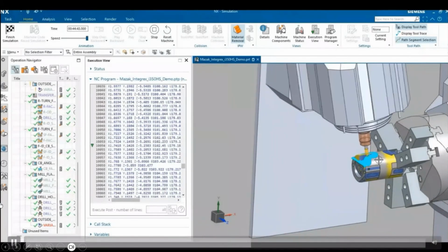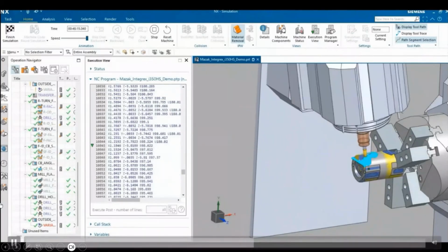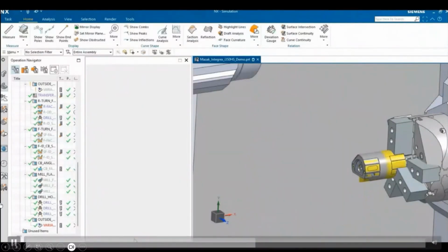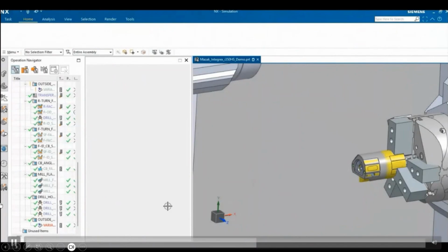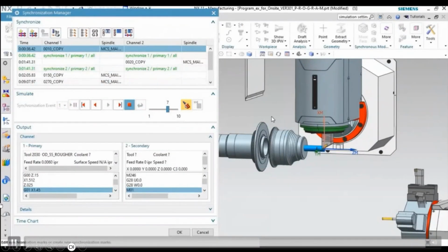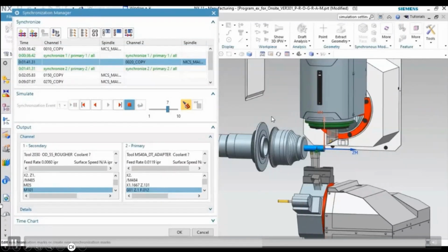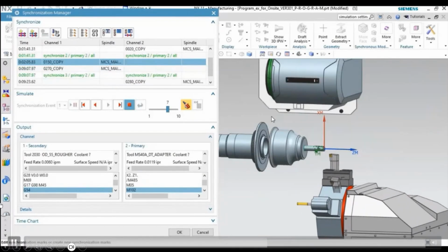This full 5-axis motion is finalizing here on this mill turn, and then we'll get our complete part represented here. Now this is a multi-channel machine, meaning it's running 2 NC programs simultaneously using sync marks or wait codes to sync up the 2 turrets in the desired sequence. You can see where the upper head is waiting for the lower turret to finish before it continues.